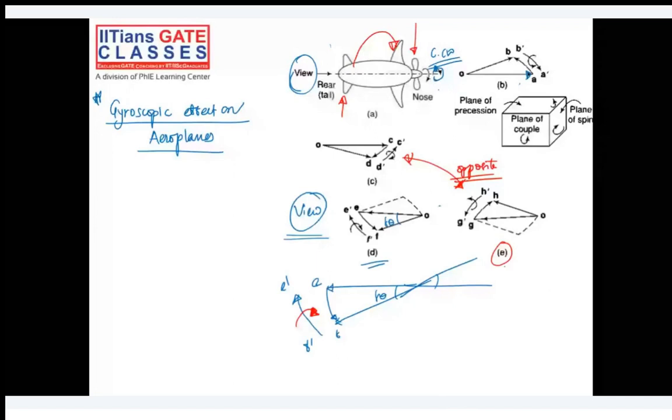They don't suddenly go down or go up, okay. Slowly they come down, or slowly they go up. So in those situations also there is a slight change in the axis of rotation of the rotor, and a slight gyroscopic effect will be there, but that is compensated by other features in the aeroplane that we don't see. That's why we don't see it. Even if you take a left turn or right turn, we don't notice it if it is not taken suddenly. The gyroscopic effect will depend on how suddenly we change the direction of the axis of rotation.